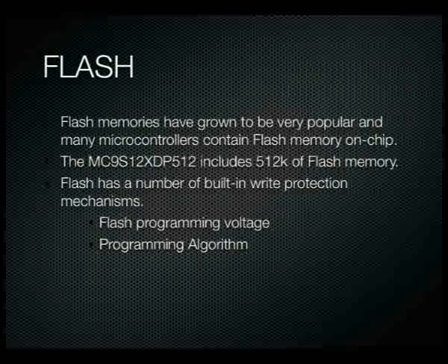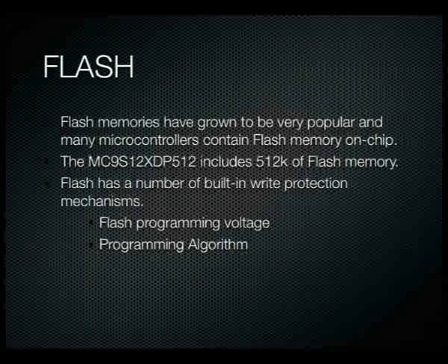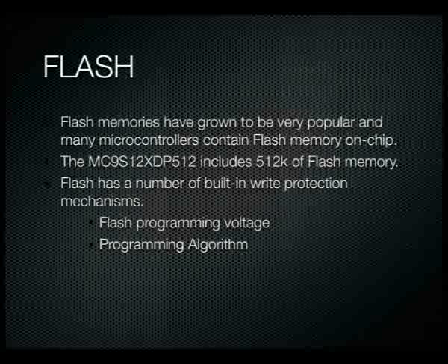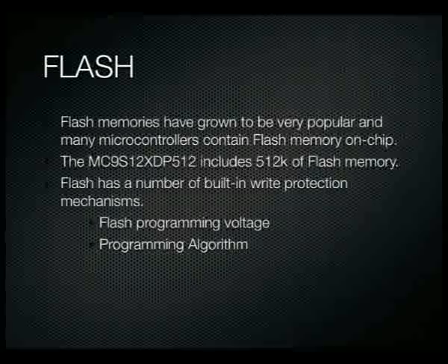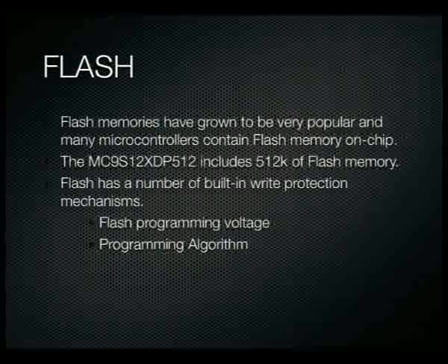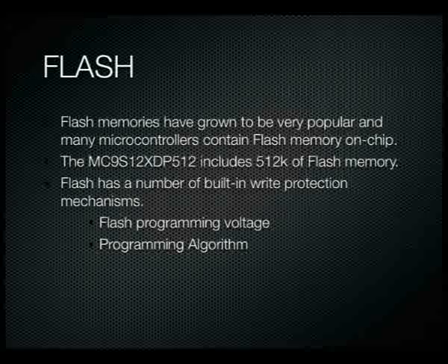But if you want to be able to rewrite your microprocessor, so to speak, while it's in an application, then you might need to provide that high voltage somehow and just ensure that under normal operation it's off, and only when you're rewriting is that high voltage provided to the chip. The other thing that they provide is a programming algorithm. Each flash technology is completely different. Each manufacturer has a different algorithm when it comes to reprogramming the flash. And reprogramming the flash generally requires you to write a certain bit combination to certain memory locations within a certain flash block.